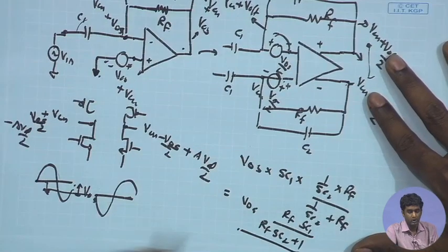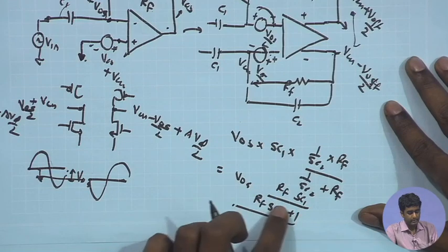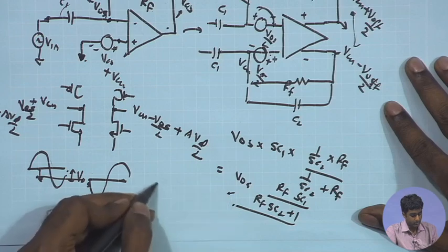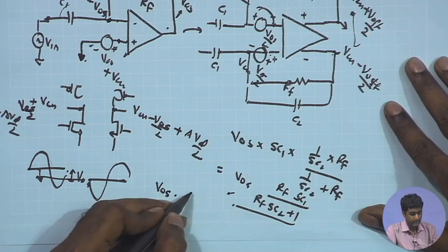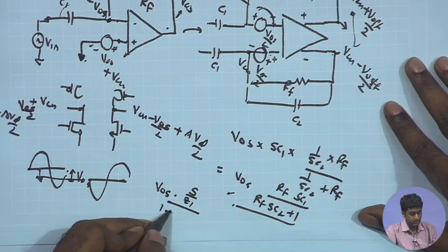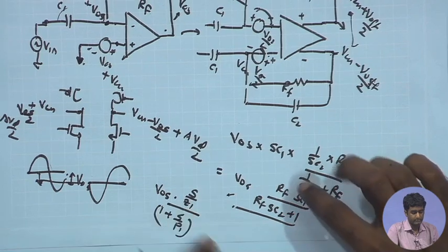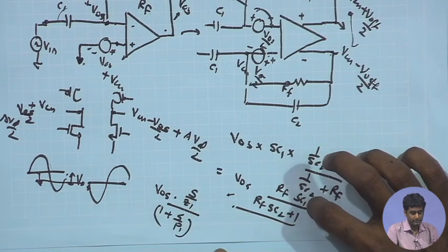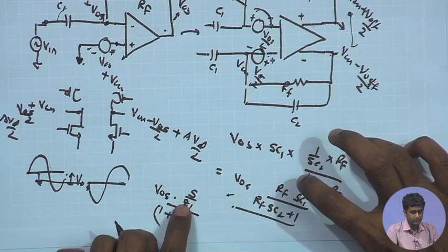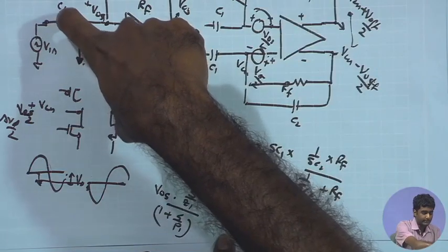This is the output coming, and once again we have two poles. We have the overall output because of V offset given by S upon Z1, and 1 plus S upon P1. Out of this, which one is smaller? The zero Z1 is set by the C1 component, and we know that C1 is going to be larger.